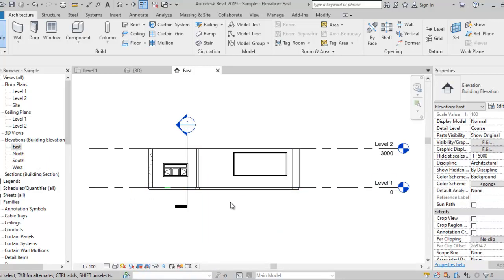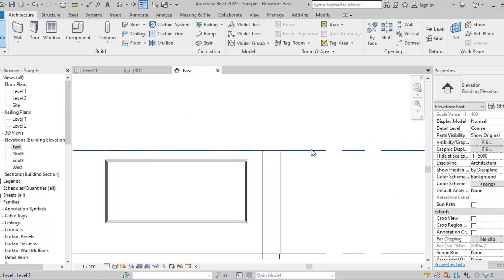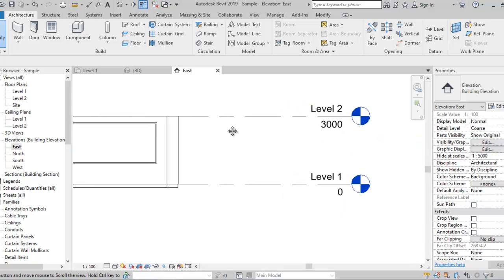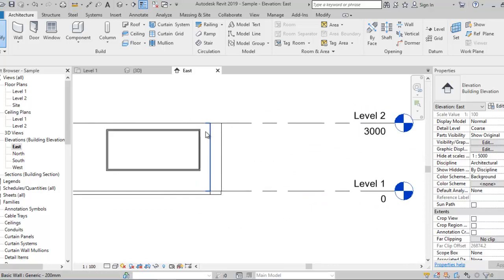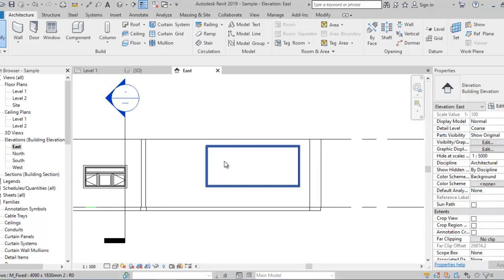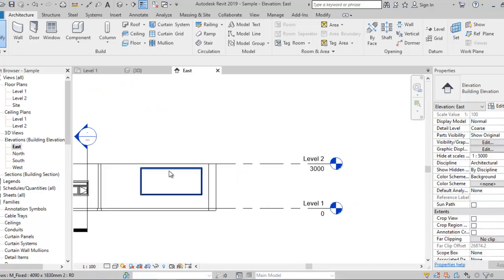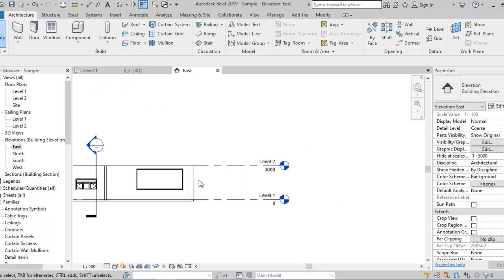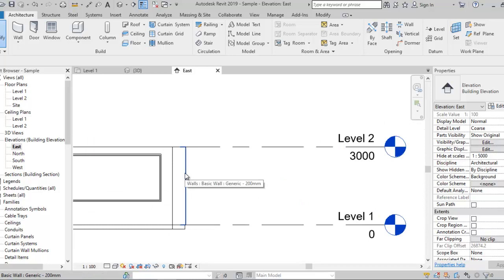and here we are going to check the level of our walls. Our walls ended at 3000, which means 3 meters. So our full ceiling cannot be more than this level. Or we can modify the height of the walls and then raise up our full ceiling. But let's make it at 3 meters.